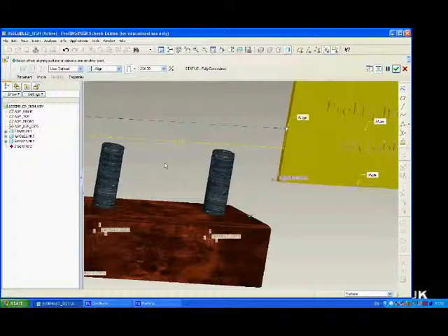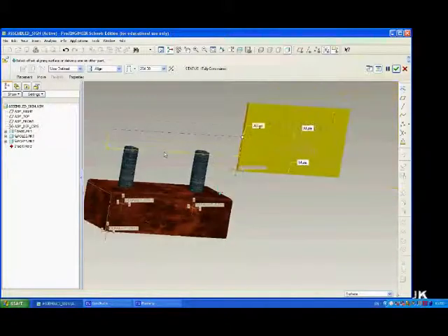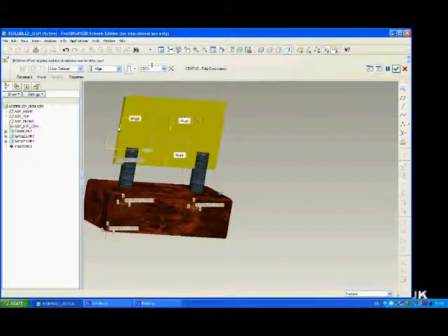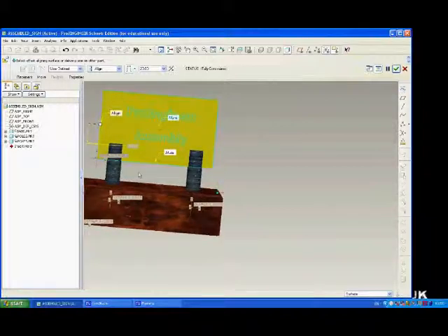The distance that we need between the pole and the face here is 20 millimeters. You can do this a couple of different ways. You can drag it to the distance between this, or even easier, you can enter the correct distance up here by typing it in and pressing enter. You can see now that our sign is in the centre of our assembly, so it's complete. Click the green button to accept.